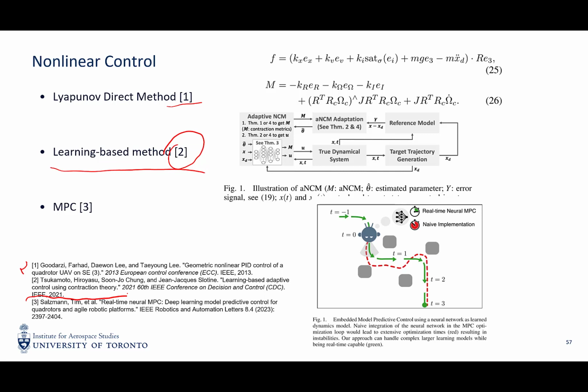The third one is MPC, called model predictive control. It's a generalization of the LQR, but for nonlinear systems. For LQR, we can calculate the Riccati equation explicitly because everything is linear. But for a nonlinear system, you have to deal with Jacobians at each different state, and you need to calculate U, which depends on the state and time. That's MPC.